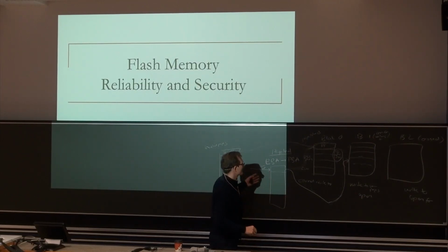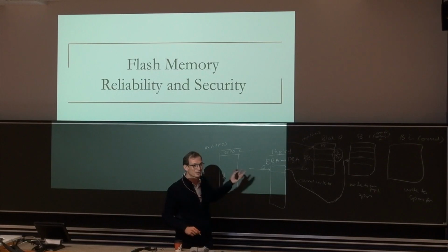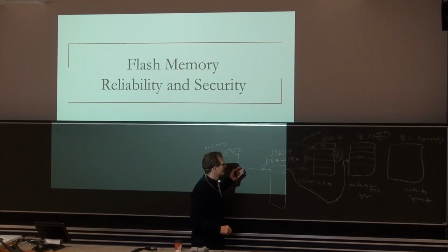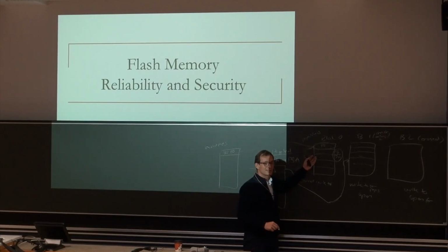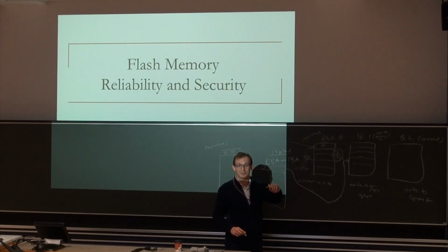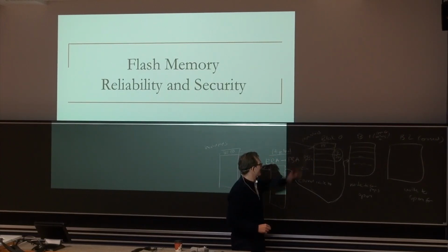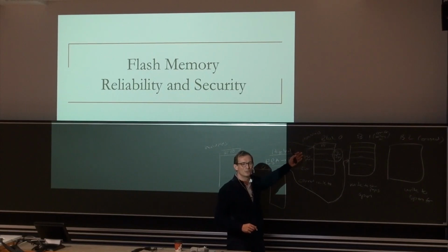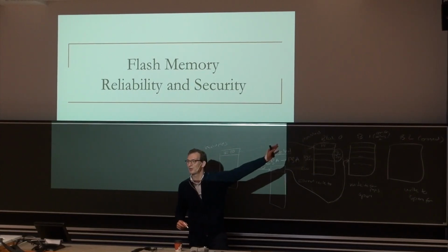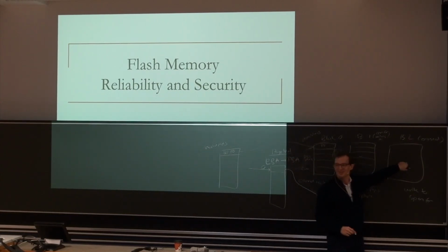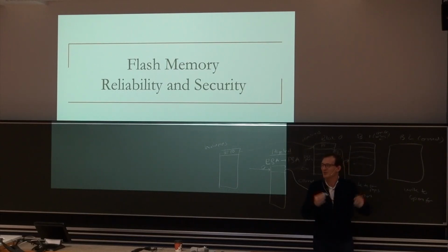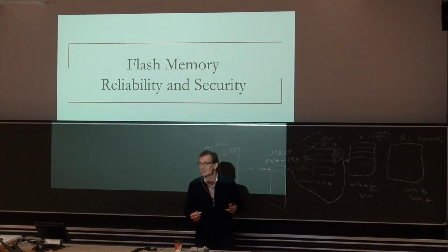So what should the controller do right now? Sometimes, this depends on the algorithm of the controller, but sometimes what the controller says is, heck, I don't want to waste a lot of this, so I'm going to move those 56 pages to a block that I erased. In the background, I'm erasing stuff because I'm smart. Make sense? So that's one way of doing it.